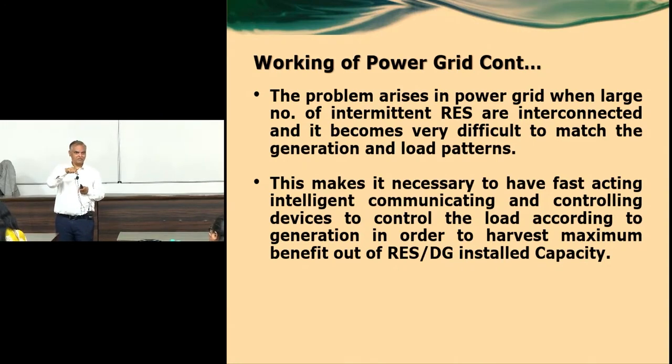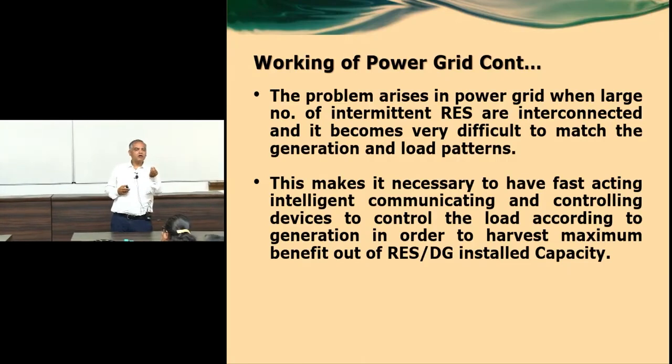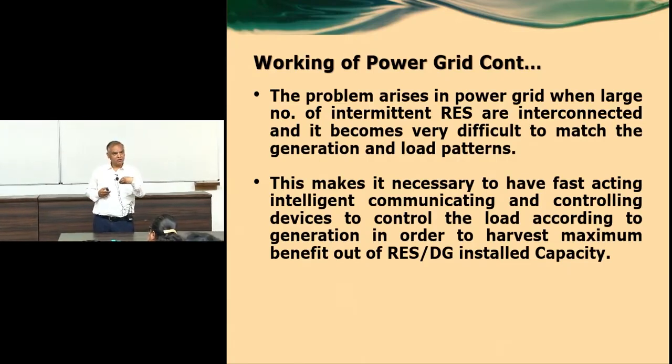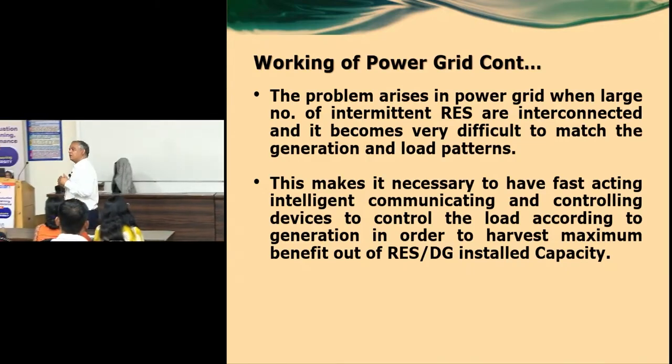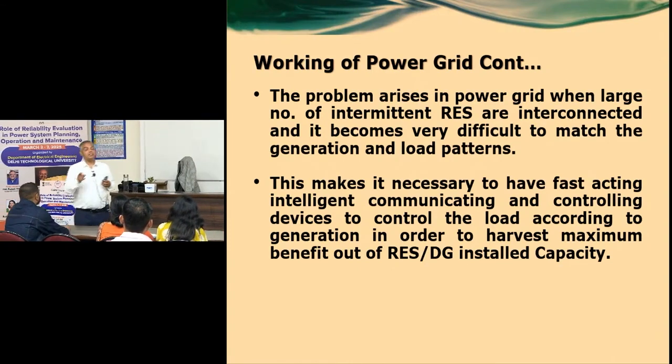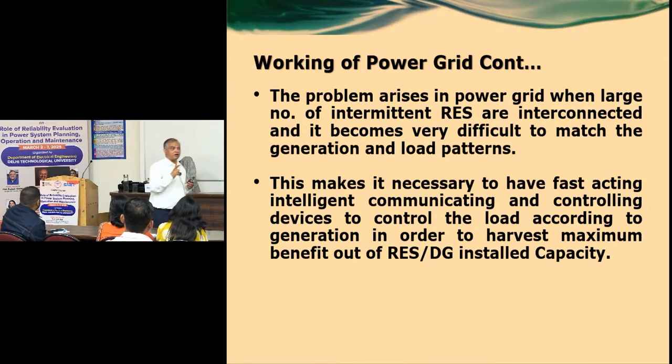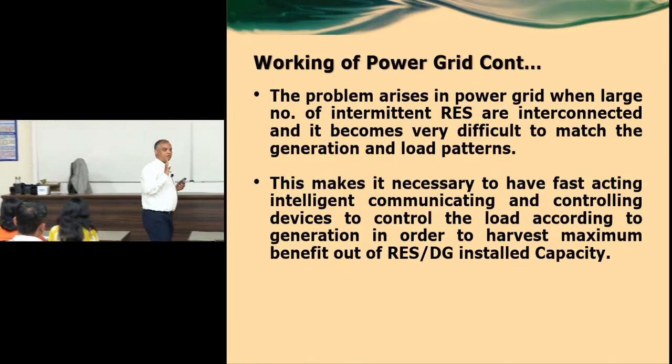The grid can have a sufficient amount of reactive power demand, but as a small appliance, you cannot sort out all the problems. But what you can do is give reactive power support in proportion to your capacity. So if n number of devices are there, and if they are controlled in such a way, then the issue of reactive power can be easily sorted out by these kinds of devices. So that's why the concept of LVRT came into picture, low voltage ride through capability.